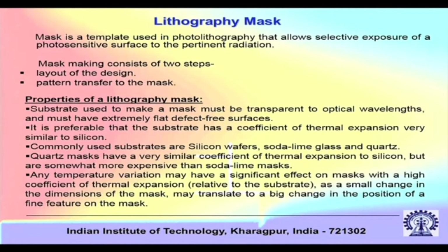The pattern is like the mask. If you have an unequal thermal expansion, then that can give rise to defects. So if you are transferring from the mask to the silicon substrate, it is good if both of them have the same coefficient of thermal expansion, so they respond to temperature in a similar way.